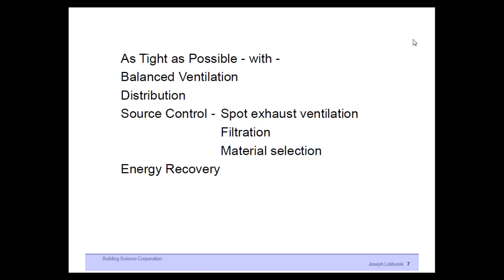This is especially the case now that ASHRAE standard 62.2 has significantly increased the ventilation rates. In the last 4 years, it has resulted in the net doubling of the ventilation flow. So we're talking about 50 to 60 CFM of continuous air change, and at 3 air changes per hour at 50 pascals, the compartmentalization number, we're talking about 20 to 30 pascal continuous negative pressures if we're talking exhaust ventilation.